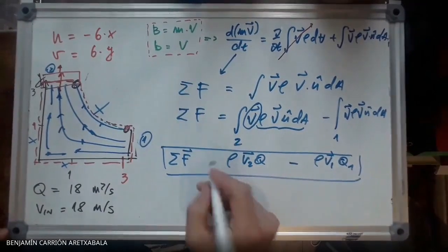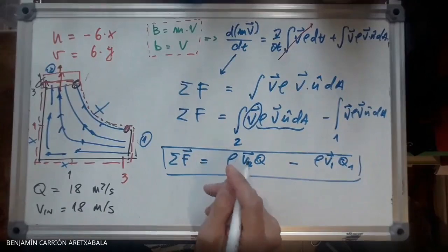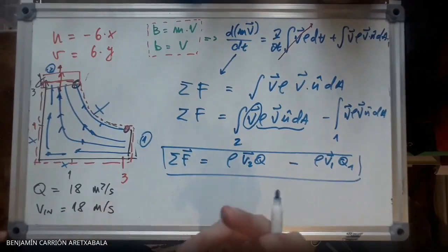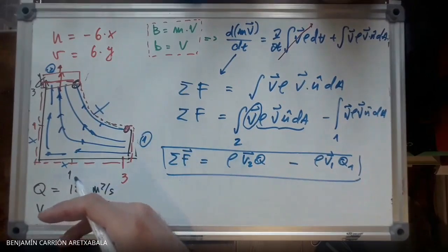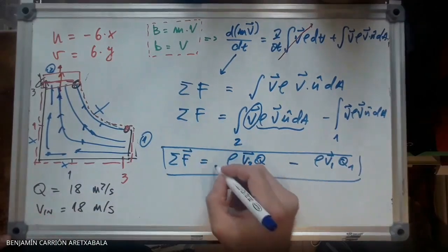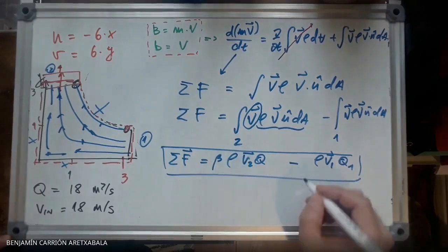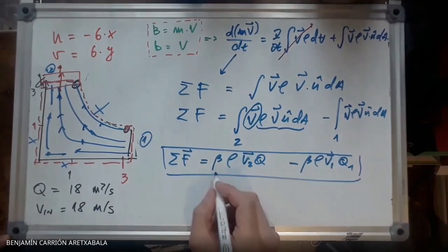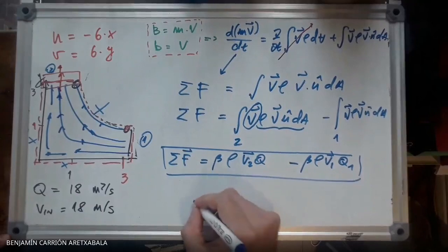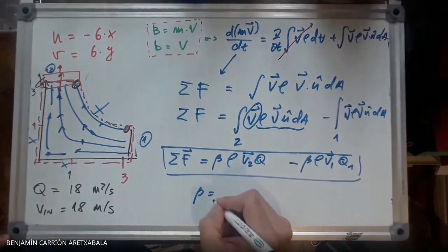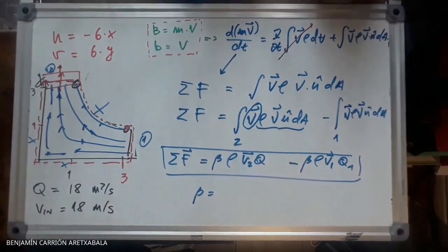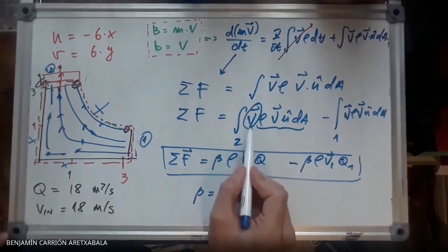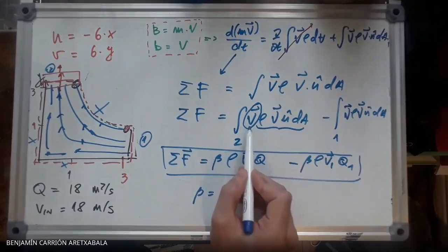But if you want a more rigorous approach, you would amplify this by a factor beta, which is a Boussinesq coefficient. So beta is nothing more than a correction coefficient, because it's not really true that you can approximate the velocity here to the average velocity. That's only going to be true under some cases.